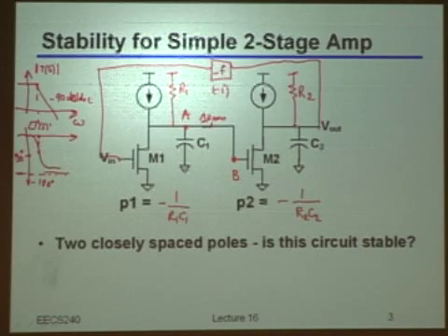So I will have some resistance and then potentially also other capacitors, parasitic capacitances in the metal layers and so on. And then potentially even in the amplifiers, because most probably the amplifiers have a bunch of transistors, not only this one that I have drawn here. So you will have additional poles and additional phase shift also in the loop. So the idea is, okay, 1 degree or 2 degrees of phase margin, they're not reliable. They're not robust at all.